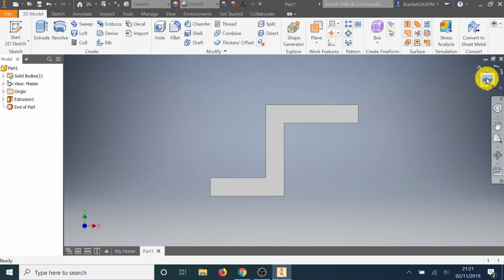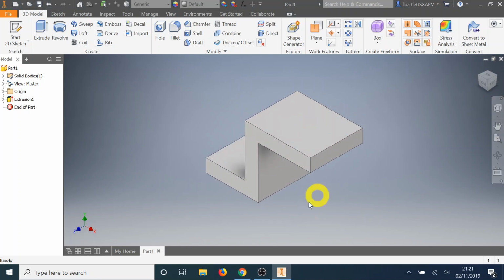We're now going to click on the top right hand corner of the view box, just the corner itself, not the face, the corner itself. Click there once, so I get this view here. I now want to tell it what I want to work on. So I want to work on this top face here, this side. I'd like to draw on that, so I need to be in 2D mode drawing on that surface.